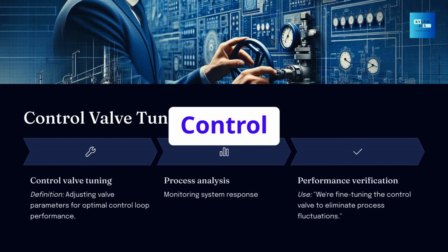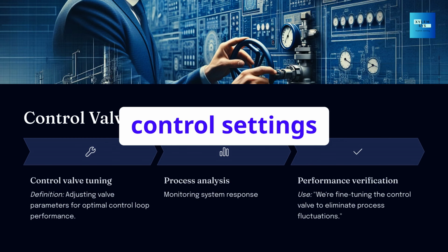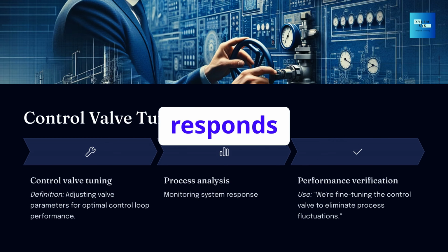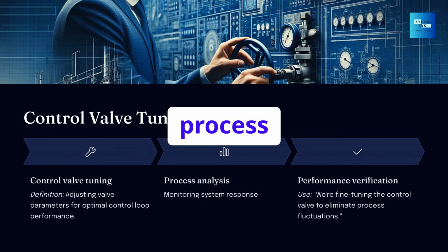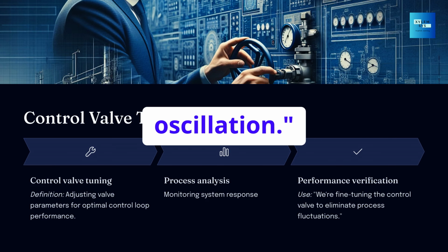8. Control valve tuning. Control valve tuning involves adjusting the control settings to ensure the valve responds accurately and smoothly to changes in process conditions. We're fine-tuning the control valve to eliminate process fluctuations and reduce system oscillation.